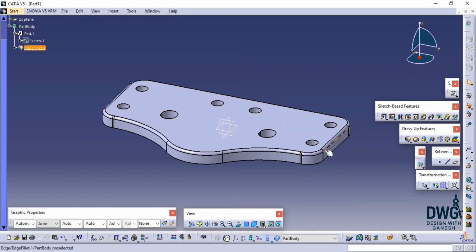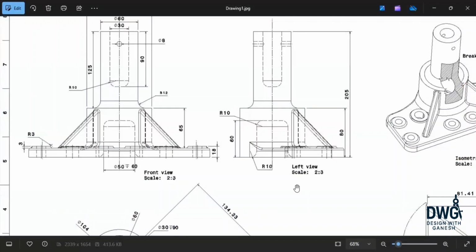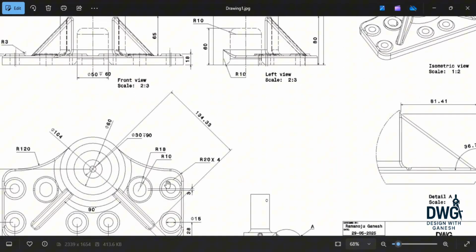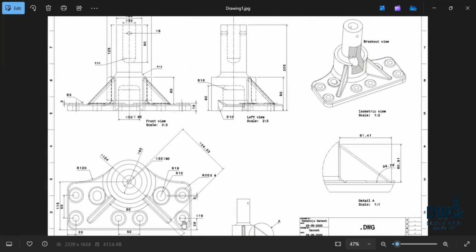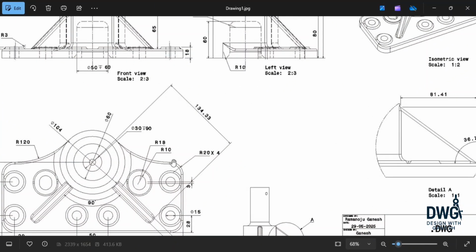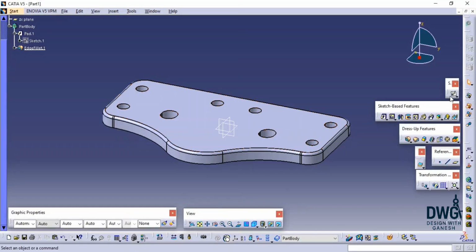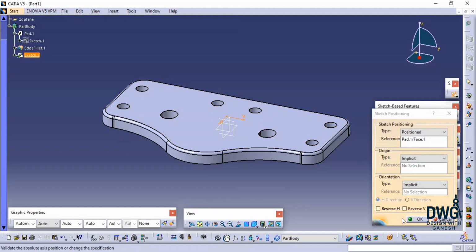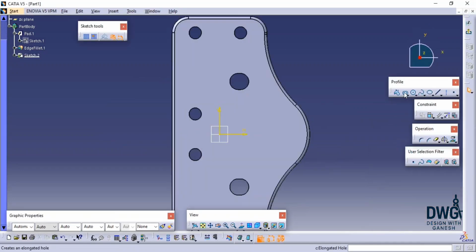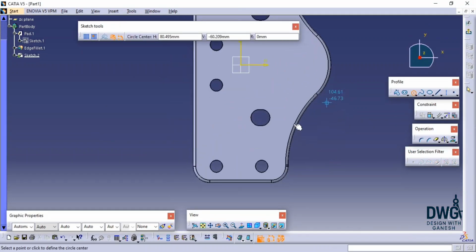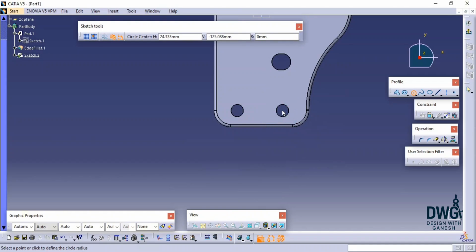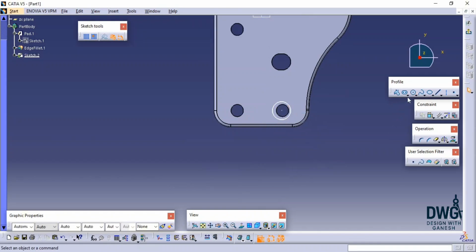Now next thing is, in the drawing at the circles there is some extension, some pad, then extrusion of radius 20. So no, sorry, the outer circle diameter is not given here, so keep it as 30. So what you do is select this plane and position sketch. Now select this circle